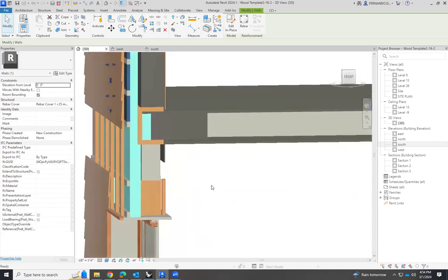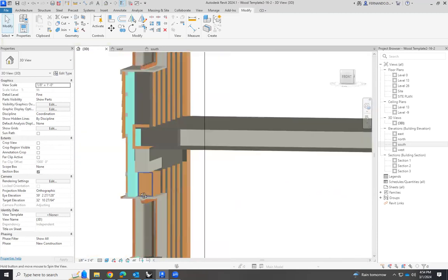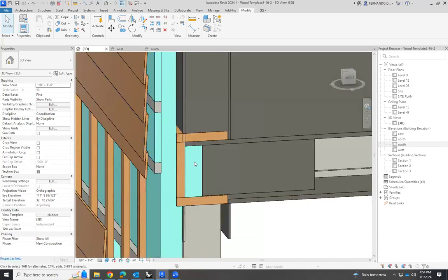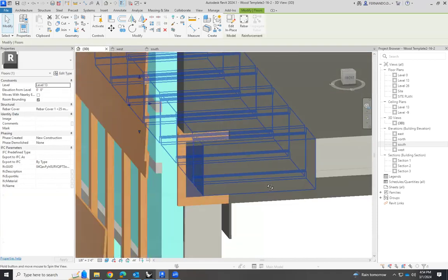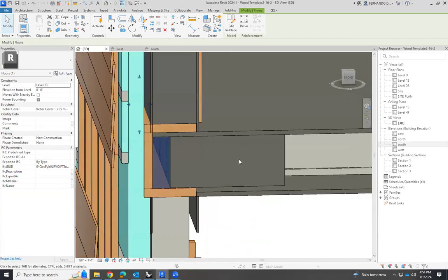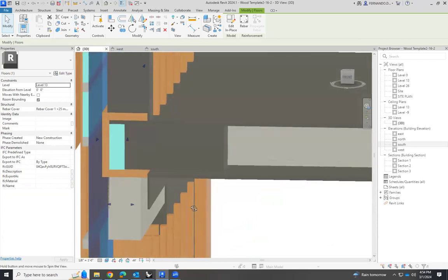The more, the merrier. Okay, so do not save money on thermal insulation because it's one of the best investments that you can do. So here we have this thermal insulation on the joists. Okay, so we have created like this U shape with wood. And we place here the thermal insulation, so the joists are in contact with this thermal insulation. Then we have wood. Then we have another rigid insulation panel here.